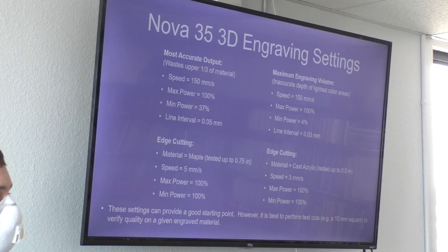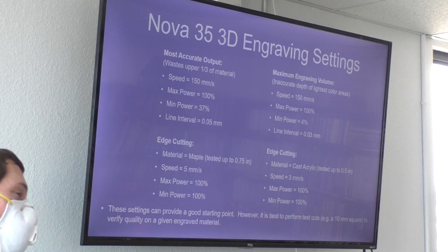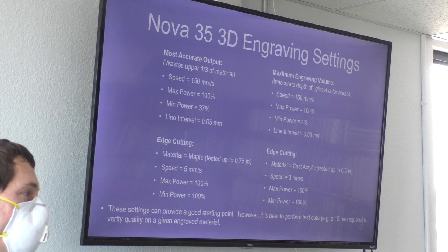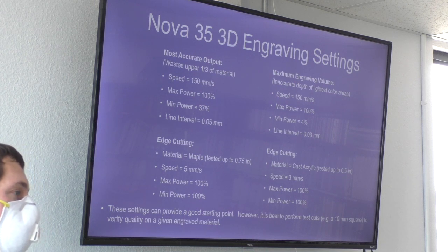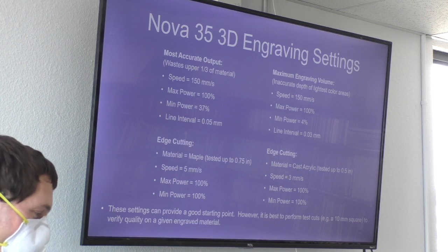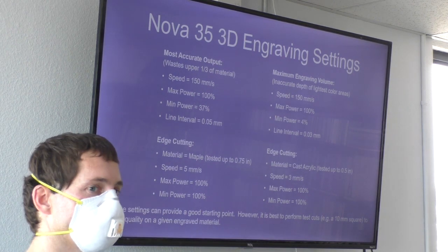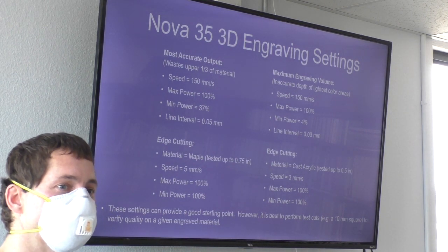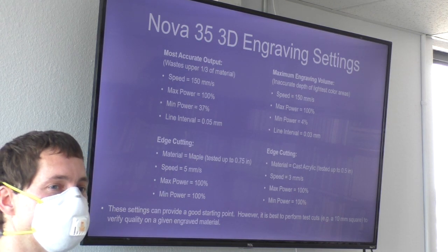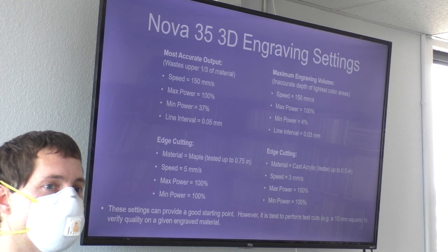On these machines, you do have a variable control on the left-hand side where you can adjust the air assist flow between a high power and a low power, and even within those high and low, you can turn it more or less. So there is a way to vary the air assist once it's started. Yes, Pat, go ahead. You might want to remind them also of the flame detection on the gantry.